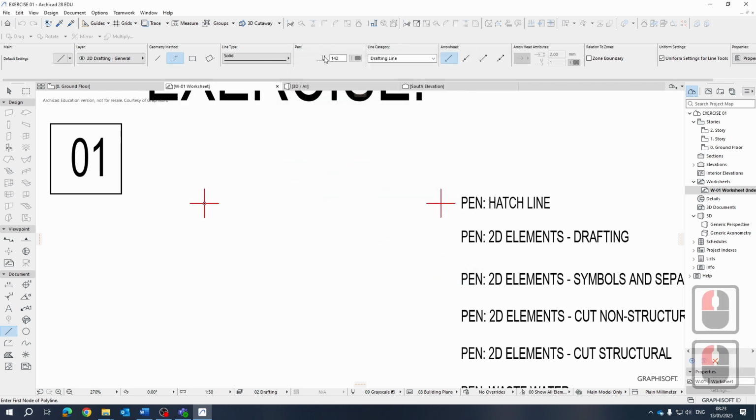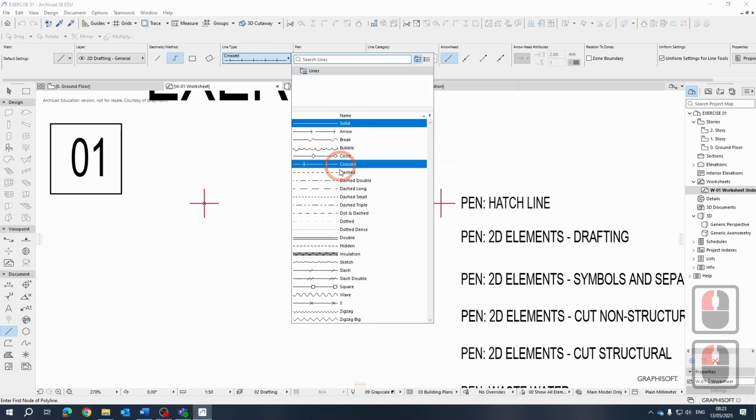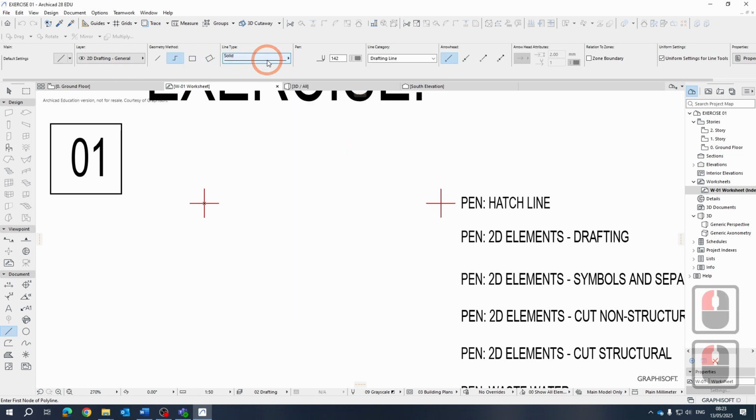All right. So Archicad has a line type that you can use, so you need to select the line type. You can use different methods, so as a single line, connected lines, or rectangles, so you can draw rectangles. So what type of geometry you're trying to draw, that's important. Just remember, for circles and that, you've got different tools to do that.